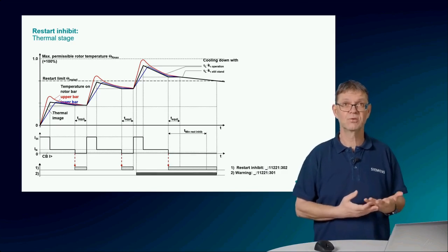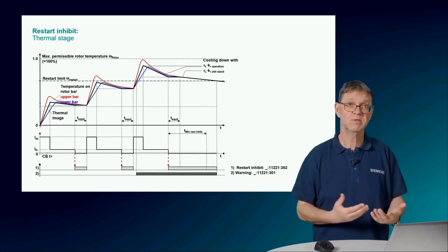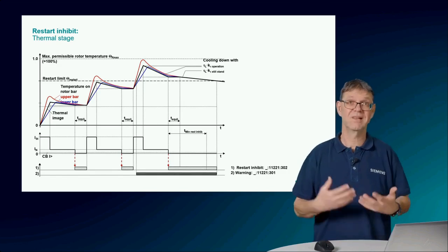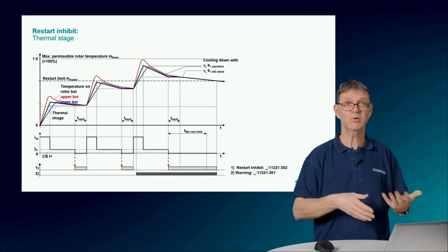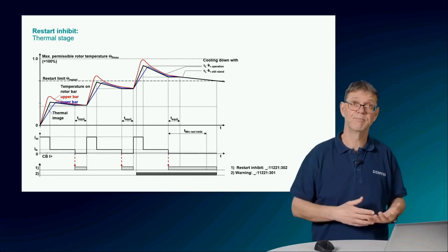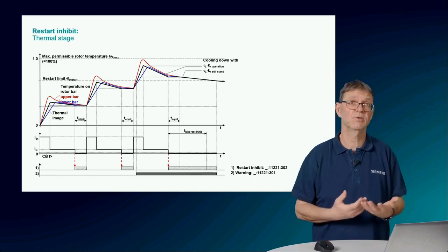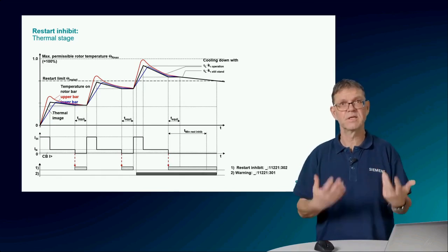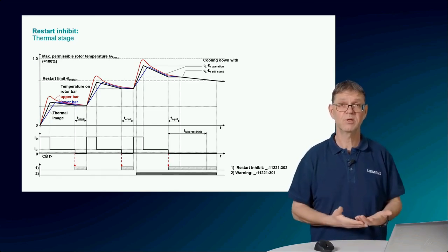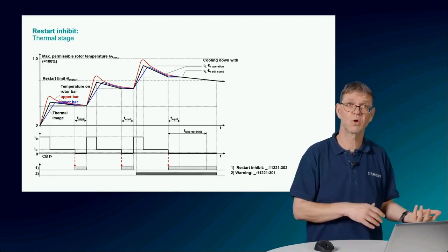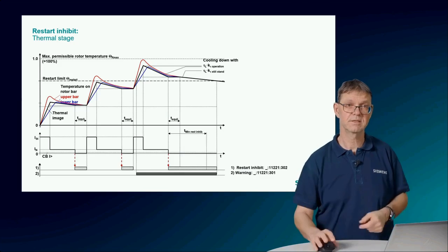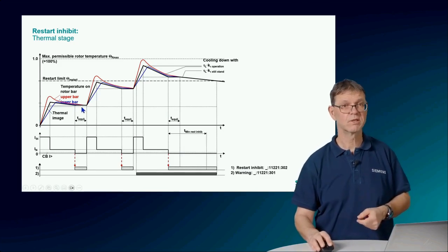What we do is to assume a kind of medium temperature, which is allowed because, based on that medium temperature, we follow just what is required, the scenario for the startup allowed by the motor manufacturer. So we have these 3 starts from cold and the 2 starts from warm. And this gives us this black curve, which we calculate.